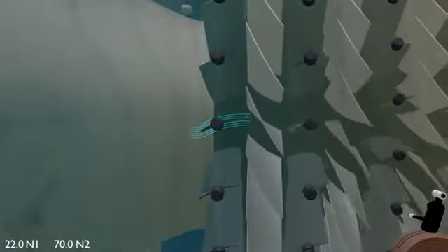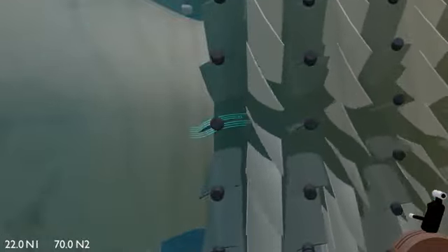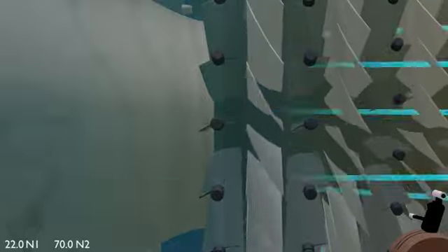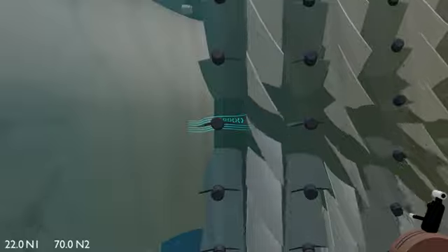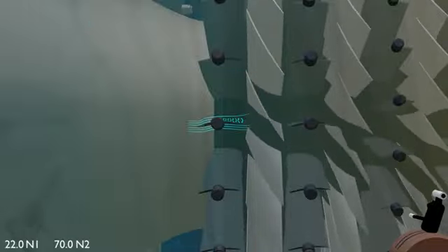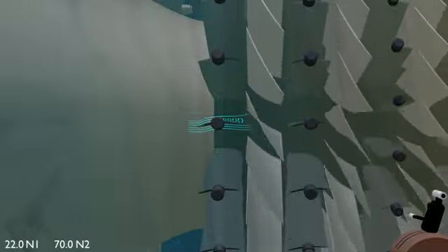Compressors are unstable at low engine speeds, and the stator vanes experience flow separation at their trailing edges. If the vane's angle of incidence is higher, then the separation increases, resulting in breakdown of airflow, which the subsequent rotor blade finds hard to accelerate.